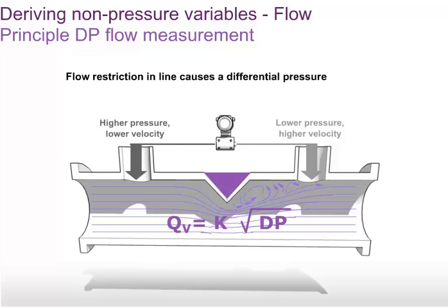Standard differential pressure transmitters can be used for this application, as long as there is no change in density due to changes of process temperature and or process pressure. As soon as the density is different from that which was used to calculate the data for the primary element, the measurement errors increase. In this case, a multivariable transmitter should be used, which measures differential pressure, process pressure and temperature, calculates the current density of the fluid, and then the mass flow.